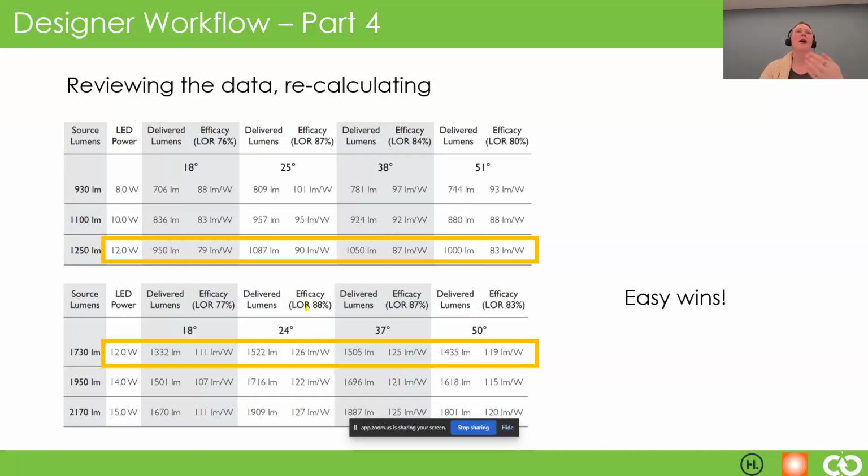And then I later realized, oh, wait, we have the same luminaire, slightly larger, in a 12 watt, but with a much higher output and a much better efficacy. Again, going back to what Max and Teresa were talking about, higher efficacy often means lower carbon footprint. And so what ended up happening is that we saved 3 kilograms of CO2 for each iteration of this fitting because we went to the more efficient one.